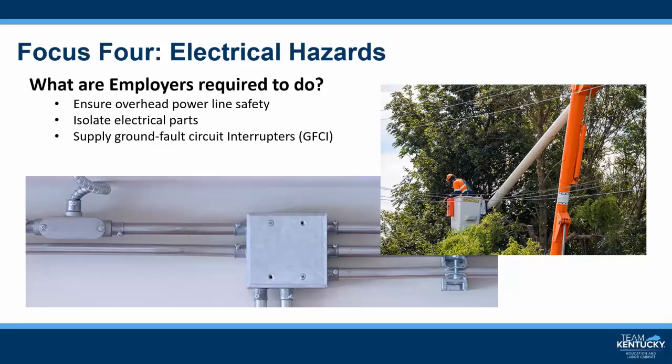Employers should train workers regarding power line hazards and about the available protective measures. Workers need to be fully informed about what jobs may have electrical hazards and the measures they will take to control the hazards. Electrical parts, conductors entering boxes, cabinets, or fittings shall be protected from abrasion, and openings through which